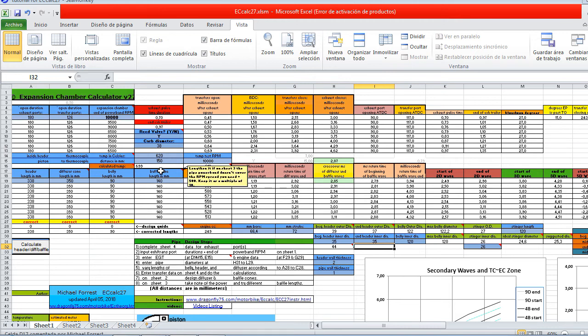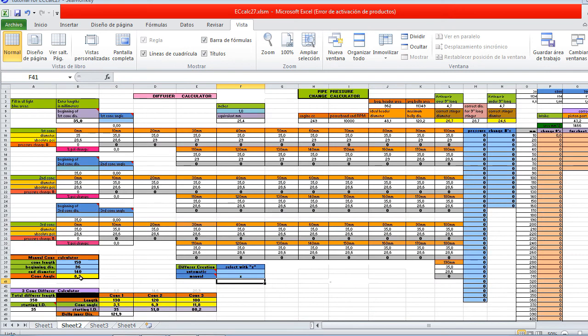And that changes the temperature a little bit, but it's not critical. Okay, so 350 diffuser length. Let's see, I'm going to make the first cone 200 millimeters. This first section right here, cone calculation goes up to 180. So when you leave the next section 2 inputs blank, it becomes a continuation of the first section. So I'm going to do that.